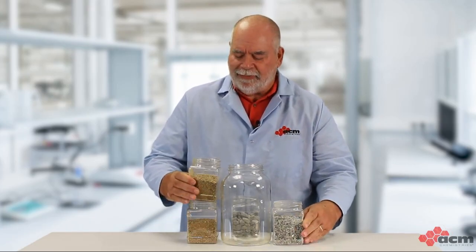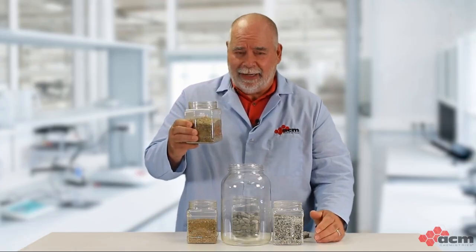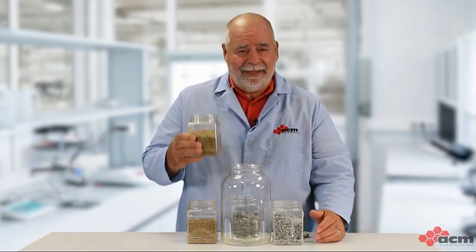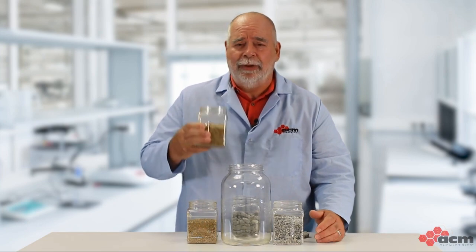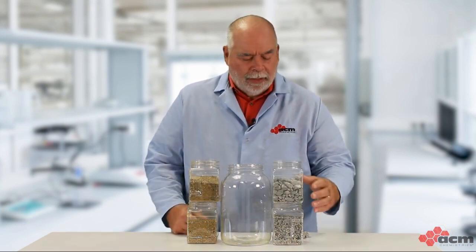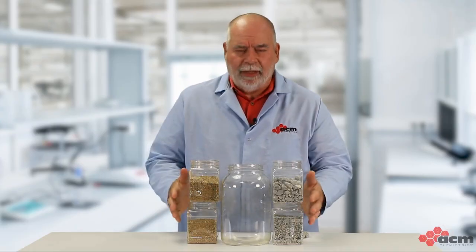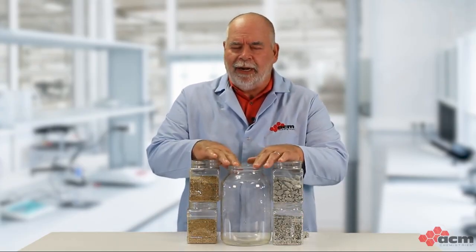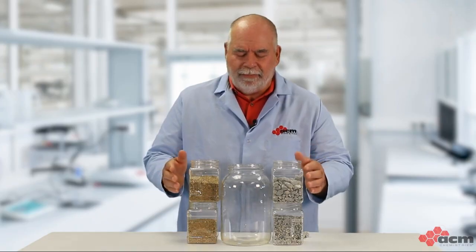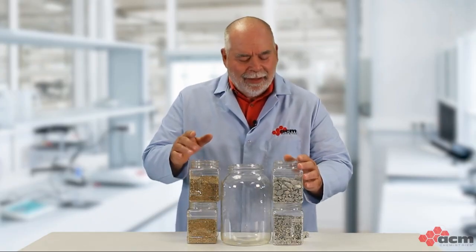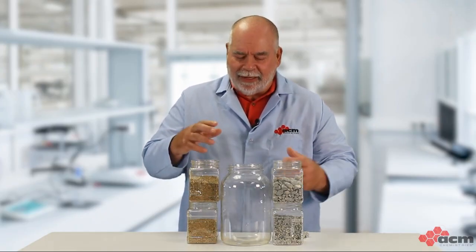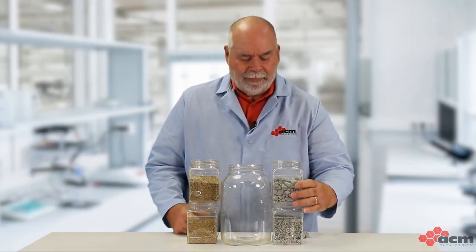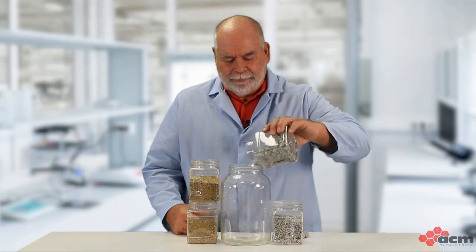And then we also have a sand here, or a fine aggregate, that we use as part of the blend to make all of your products as dense as possible and as low in absorption as possible. So now what we're going to do is take all of these aggregates we just talked about. We're going to put them in our blending jar here, which would be a little bit like your mixer, not exactly like your mixer. And then we're going to show you how these aggregates fit together and try to make a dense product. Start with a large aggregate.